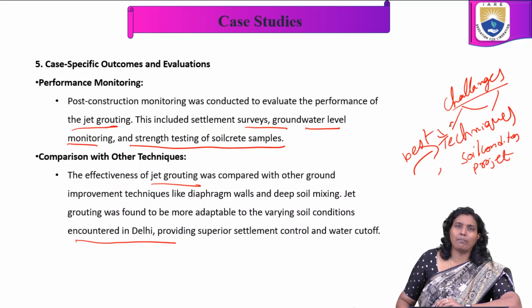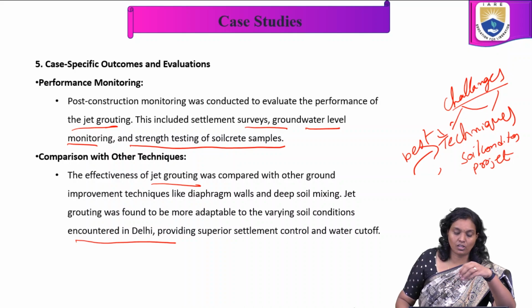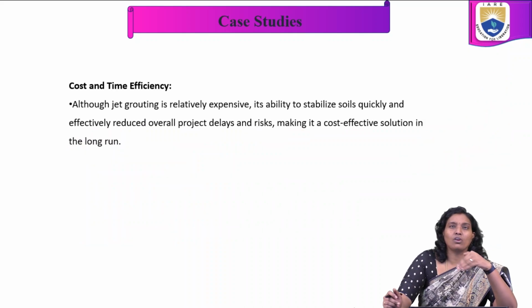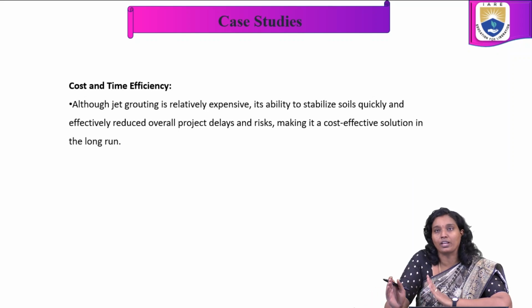So this is the comparison. In this kind of soil condition, we may choose deep soil mixing also, but jet grouting was found more adaptable for these particular conditions. And although jet grouting is relatively expensive, its ability to stabilize soils quickly and effectively reduces overall project delays and risk, making it a cost-effective solution in the long run.